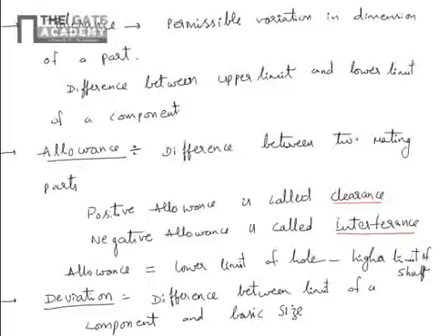So what is basic size? Basic size is also called nominal size. It is the standard size with reference to which the limits of variation of a component are measured. If you calculate the diameter of a shaft to withstand some certain speed, you may get 44.95 mm diameter, but that is the actual size, based on design value.